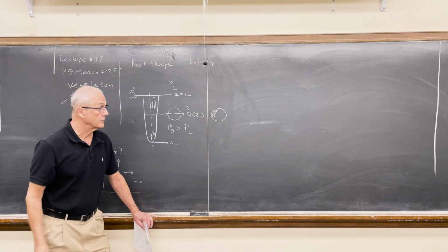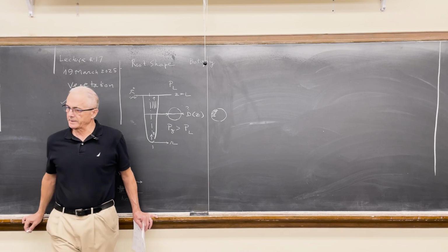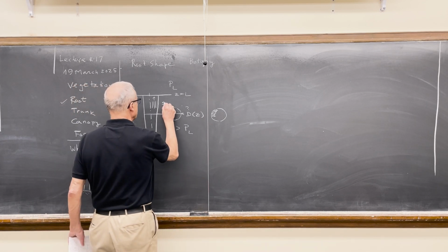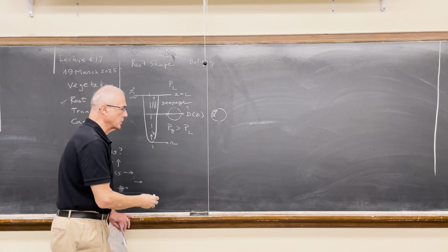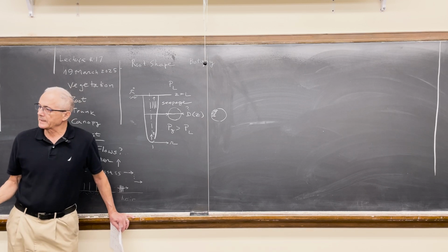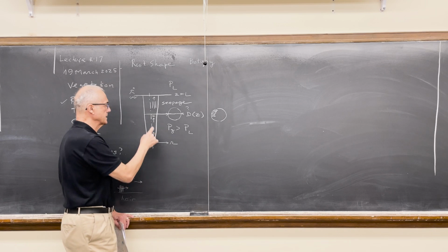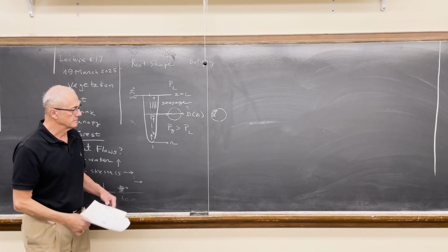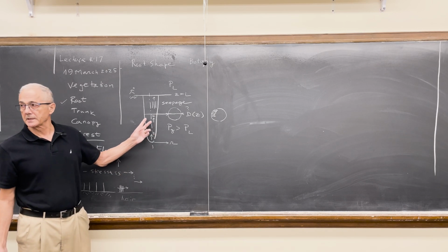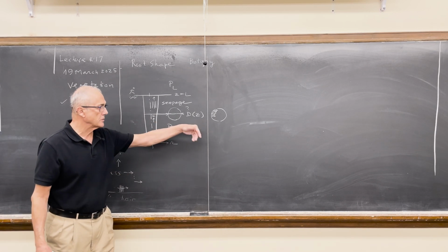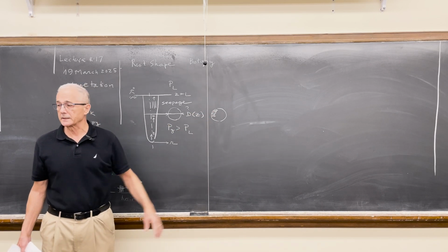And obviously, water flows upward with great difficulty. It seeps upward. Seepage. And it seeps upward with an average speed called U. This U is like in fluid mechanics, the average speed in this body averaged over all these non-uniformities, meaning tubule and the solid.